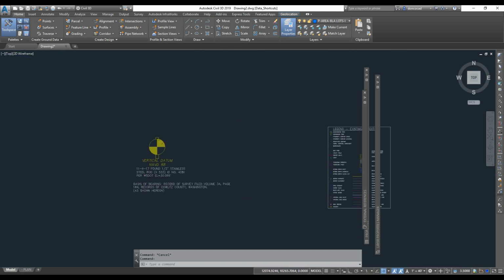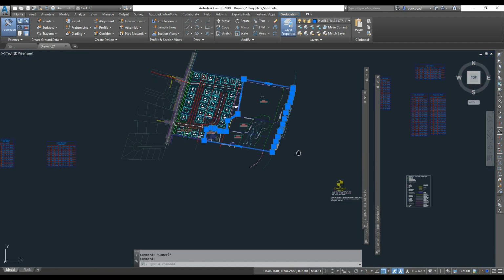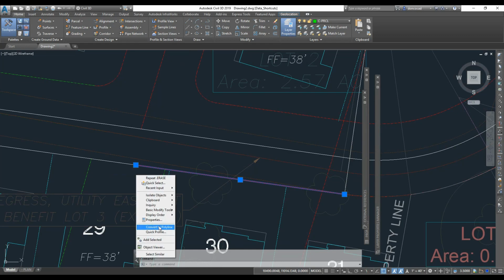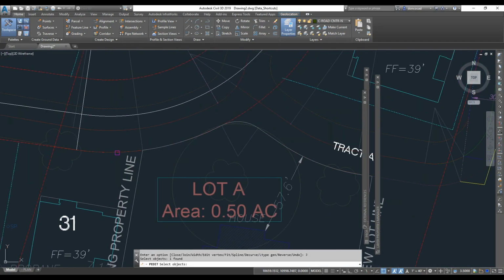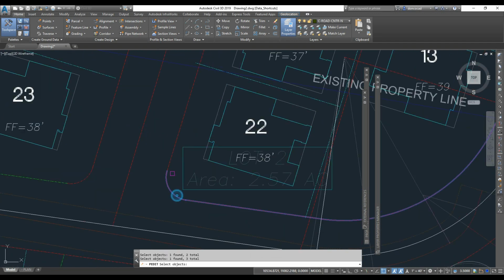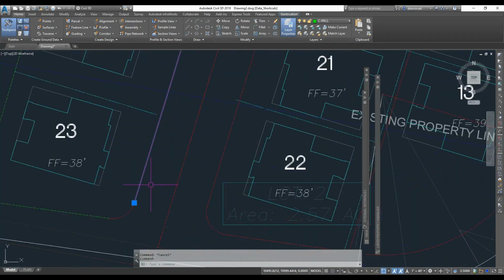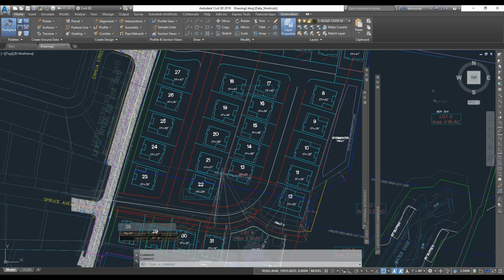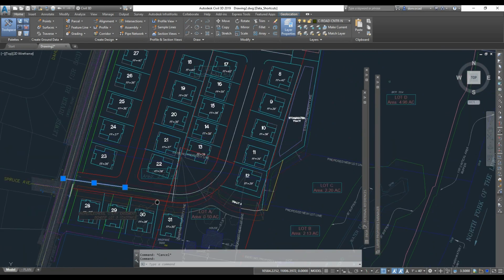This is in model space and existing conditions base file, which is a 2D file off the survey and other composites that we're going to use to XREF in. So what I'm going to do is clean up these lines here right away and connect all these, fillet the intersections in, and then check my geometry, and clean up what we have.